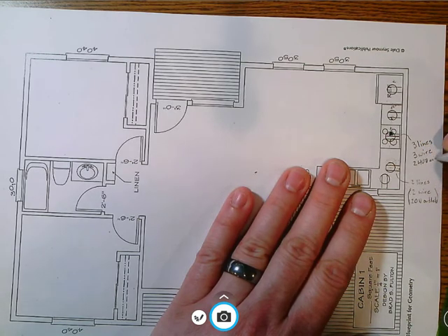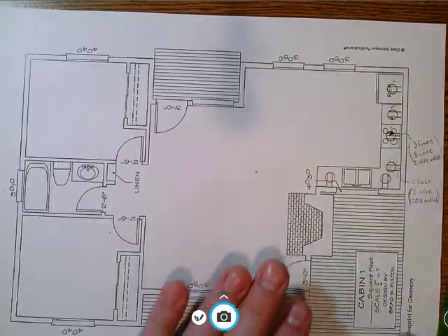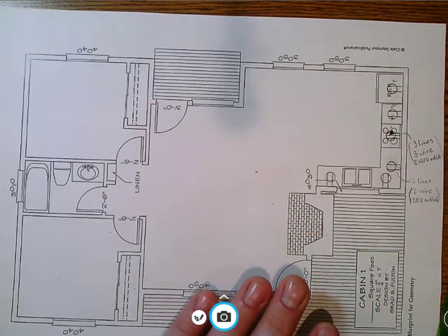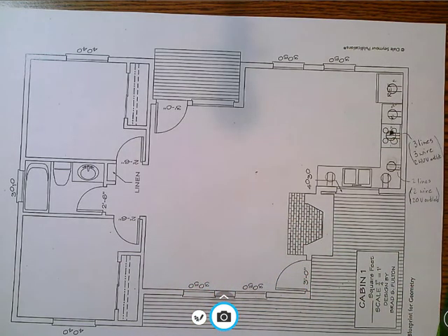If you ever buy wire from a hardware store like Menards or Home Depot, and you buy a 2-wire chunk of wiring, you'll notice that they have 3 wires, and 3-wire has 4 wires. The reason for this is that all of these electrical cables have a ground in them, and it's just a pure copper wire with no coating on it.